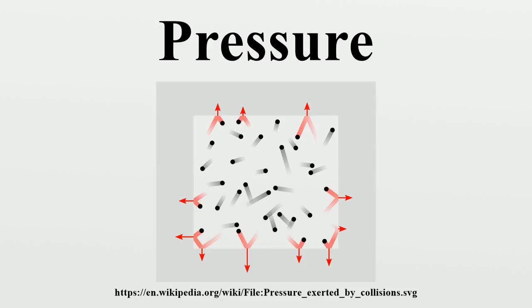10 MSW equals 32.6336 FSW, while 10 meters equals 32.8083 feet. Gauge pressure is often given in units with g appended, e.g. kPa(g), bar(g), or psig, and units for measurements of absolute pressure are sometimes given a suffix of a to avoid confusion. For example, kPa(a), psia.